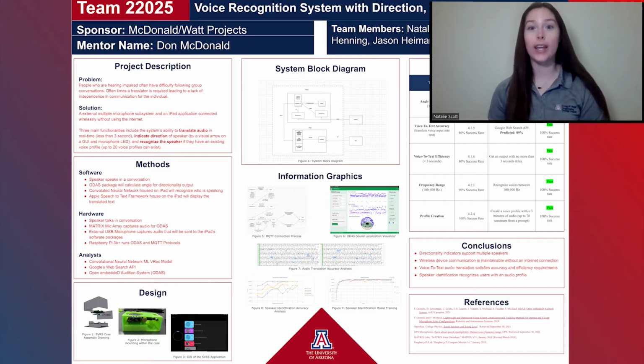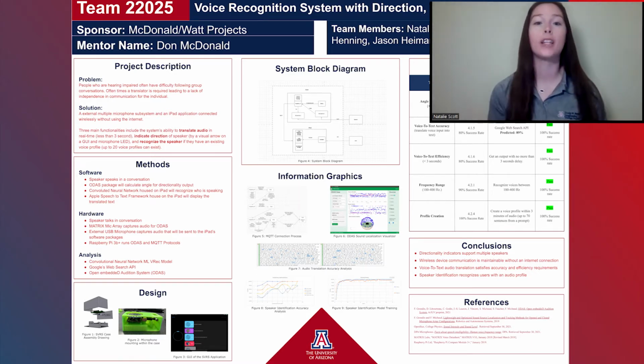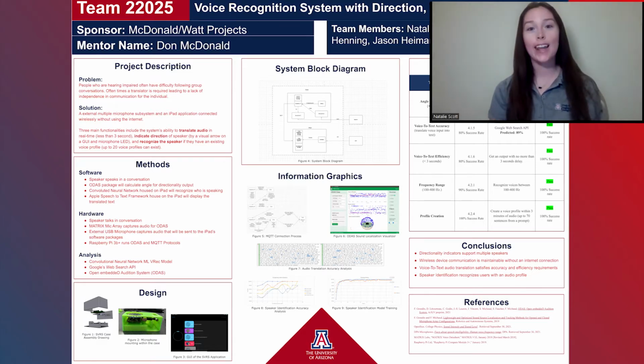And thirdly, we also realized that our Bluetooth connection between our Raspberry Pi and our iPad was not going to have the correct bandwidth to be able to actually transport audio files between the two subsystems, which led to our new idea of information transfer, which we decided to go with the Message Queuing Telemetry Transport (MQTT) that utilizes an ad hoc network that we could create using our Raspberry Pi.